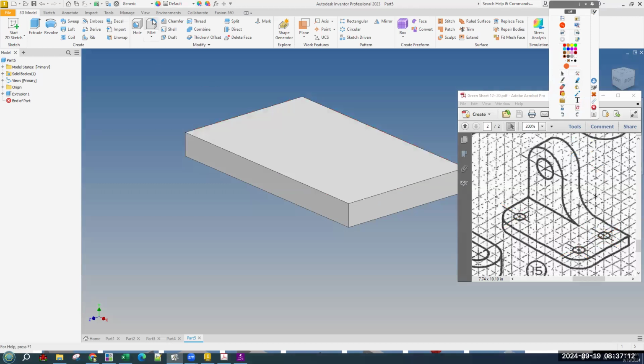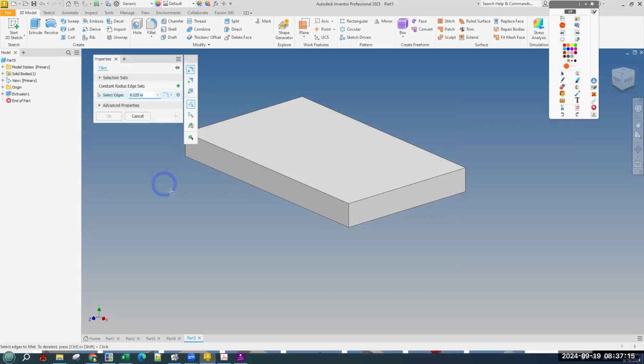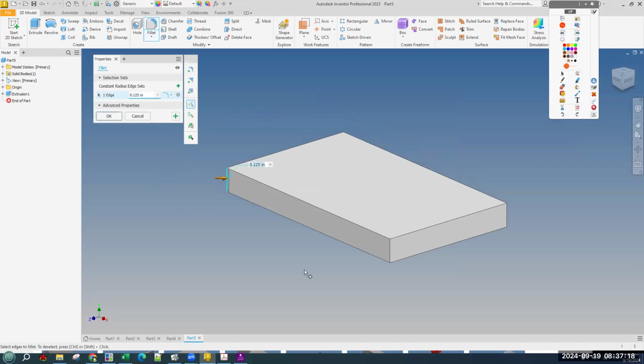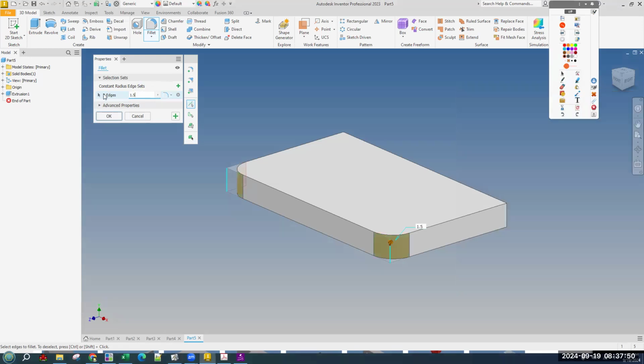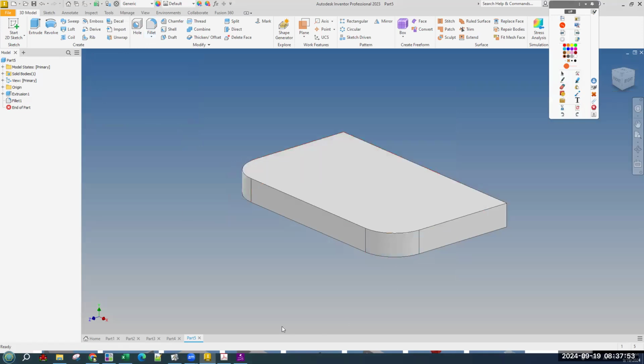So let's just go ahead and get the fillet tool. And the edges we want to fillet are these tiny vertical ones, that one and that one. And if we do them both, they'll have the same dimension. And the dimension that we want is, like I said, 1.5. These lines that stick out past are construction lines, or again, center mark lines. And they show us where the center point is. And if you count through, it's 1.5. And there we go. So we have our front edges.